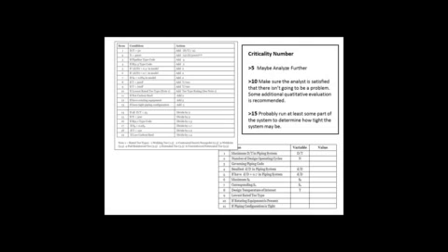If the number is greater than 5, then maybe we need more advanced analysis. If the number is greater than 10, then we probably want to look at the SIFs and the Ks that we have and see how accurate our existing calculation is for them. And if the criticality count is greater than 15, we probably want to run FEA tools on that system.